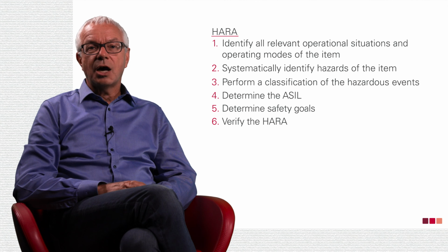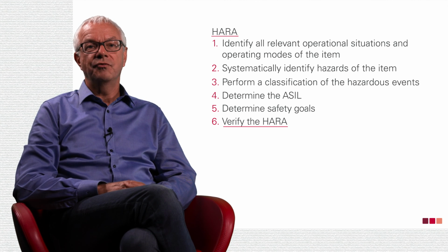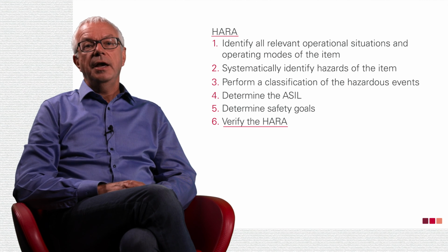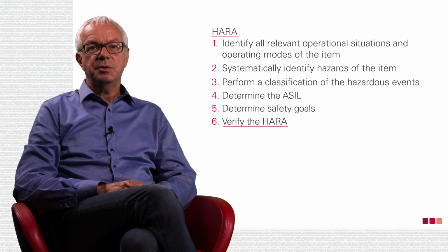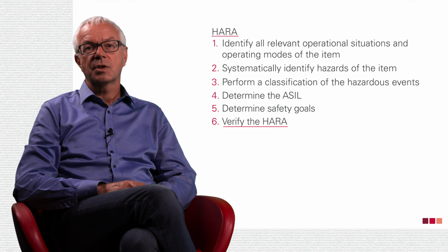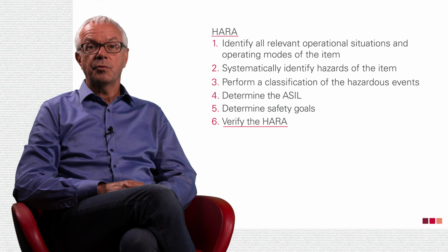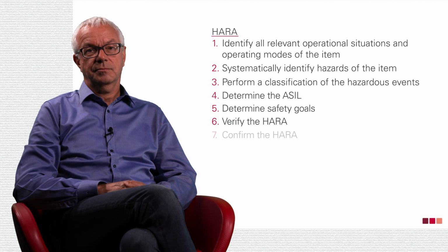If you've carried out and documented the HARA, you must subject it to verification according to the rules of ISO 26262 Part 8. A review team must, for example, check whether sufficient and reasonable hazardous situations have been considered, whether this is consistent with the safety goals, and whether the HARA procedure has been applied correctly.